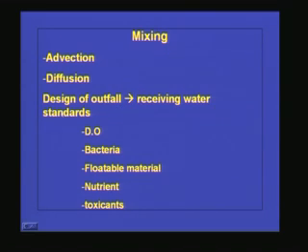Whenever we design the outfalls, the receiving water standards on dissolved oxygen, bacteria, floatable material, nutrients and toxicants should be satisfied, because all these water bodies have a lot of aquatic organisms. So the dissolved oxygen concentration should not fall below the specified minimum.